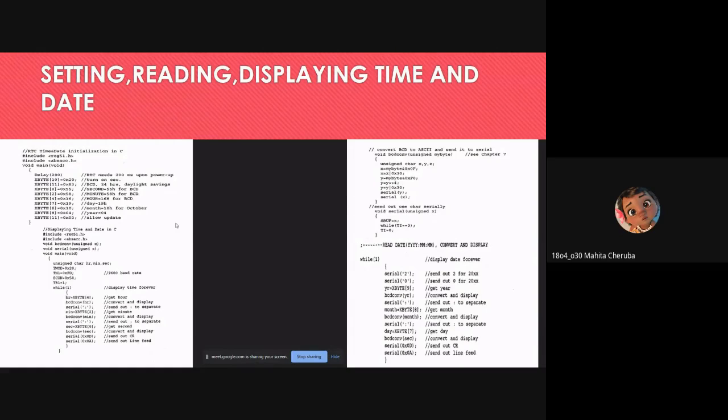We put this in 10. It denotes register A's address, and then we are putting 20 in it. So we are using 0x here. Why we are using x is to indicate that it is a hexadecimal number. So we know that 0x10 we are writing as 80, and the same procedure goes for writing the B register address 11 and to set the timer mode.